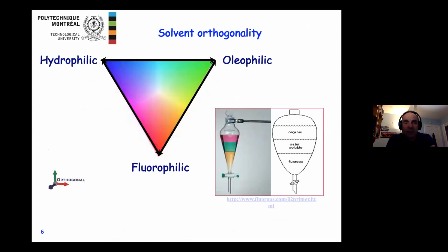What we did here, we used another family of photoresists. We didn't use the traditional photoresists that are used in lithography, but we used fluorinated materials. As you can see here in this slide, the reason to use that is that we don't want these materials to chemically interact with the organic material. So if we use traditional photoresist, this would significantly deteriorate the properties of the organic semiconductors.